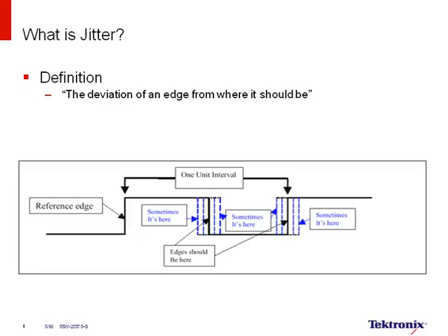Peak-to-peak jitter is really a statistics definition. So when you think of statistics like average or standard deviation or min or max, well, peak-to-peak is really max minus min. So on slide number 4, it's really the difference between the, shall we say, the worst case measurement, whatever it may be, period, frequency, minus the smallest. So that's peak-to-peak. It is a statistic. So you could have peak-to-peak for cycle-to-cycle, peak-to-peak for period. It doesn't really matter. It's a statistic.